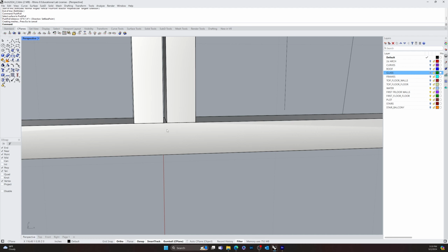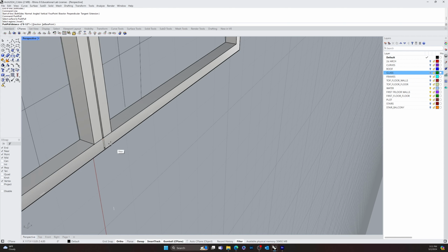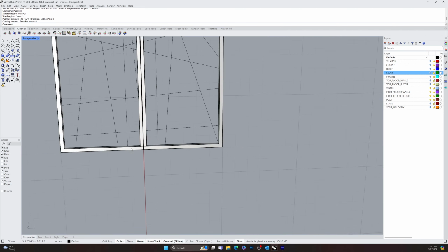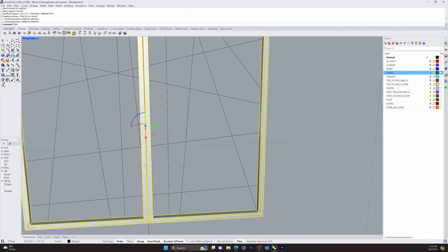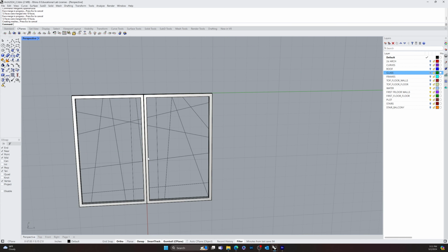Because then you get a rectangle, Boolean, extrude, and Boolean difference, and get all those measurements right. But now you just go line, line, push pull. Okay. Merge all coplanar faces.